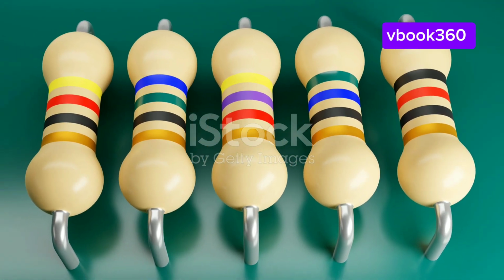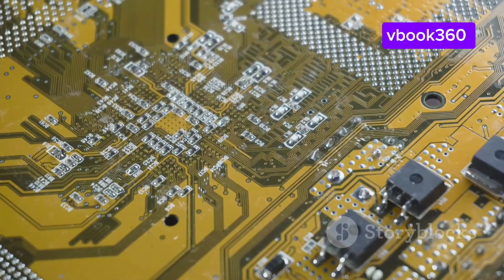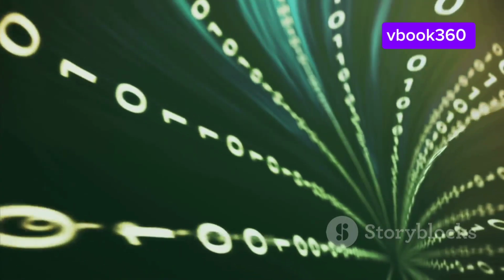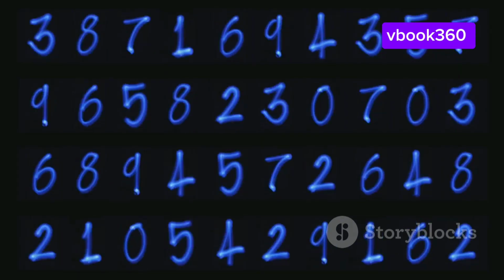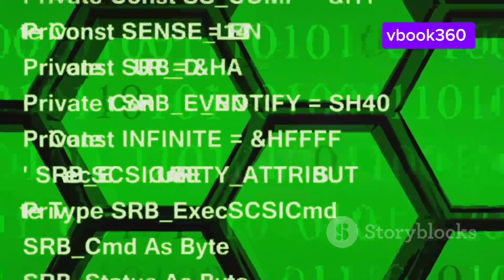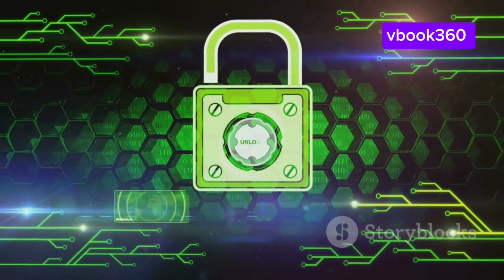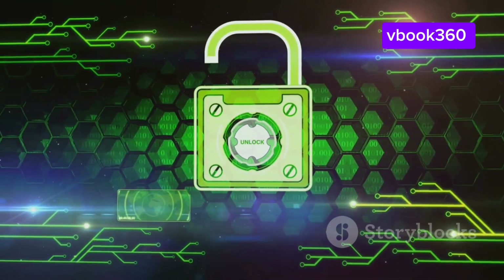The most common type of resistor utilizes a 4-band color code, where each band represents a specific digit or multiplier. Starting from the band closest to one end of the resistor, the first 3 bands indicate the significant digits of the resistance value: black 0, brown 1, red 2, orange 3, yellow 4, green 5, blue 6, violet 7, gray 8, white 9. The 4th band, separated slightly from the first 3, represents the multiplier, which determines the order of magnitude of the resistance value.